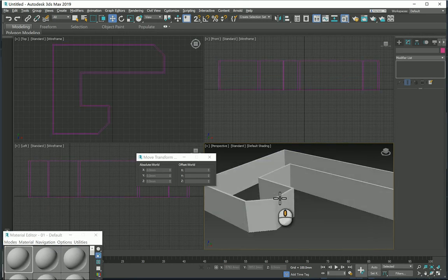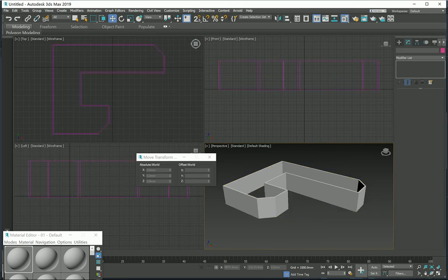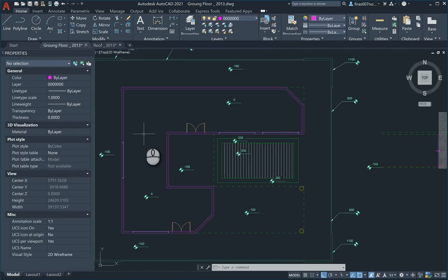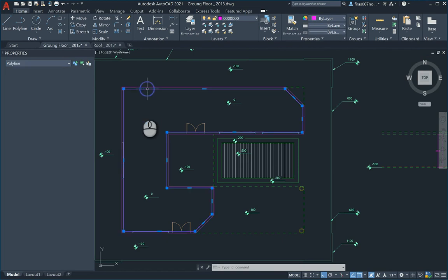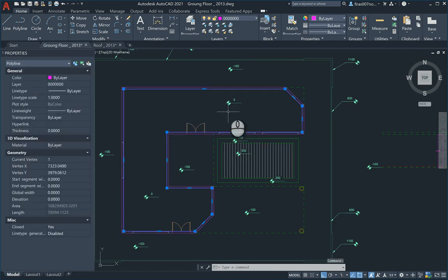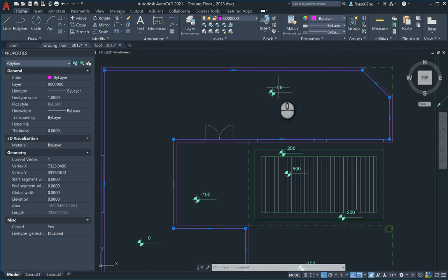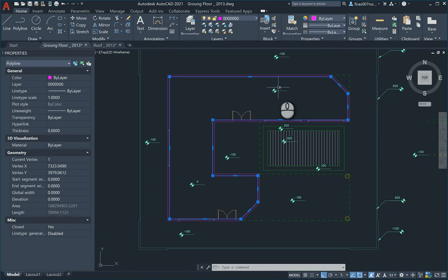Now we'll go back to AutoCAD, and okay, now the inside wall, the inside slab is this one here. It's located on level 0, and that applies to the second rule, which is horizontal surfaces. The Z value or the level is the same as written in AutoCAD, and the extrude should be -200 or 300, depending on the case.